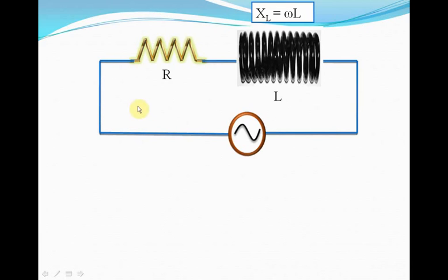How do we calculate that? Well, Vrms is given, isn't it? And Irms is Vrms divided by Z. There's no doubt about it. So we have to calculate the net impedance of this circuit. When we have done that, we can simply say that IRMS is VRMS by Z, isn't it? And similarly, we can also try to calculate the phase angle by which the voltage leads the current, by drawing phasors.